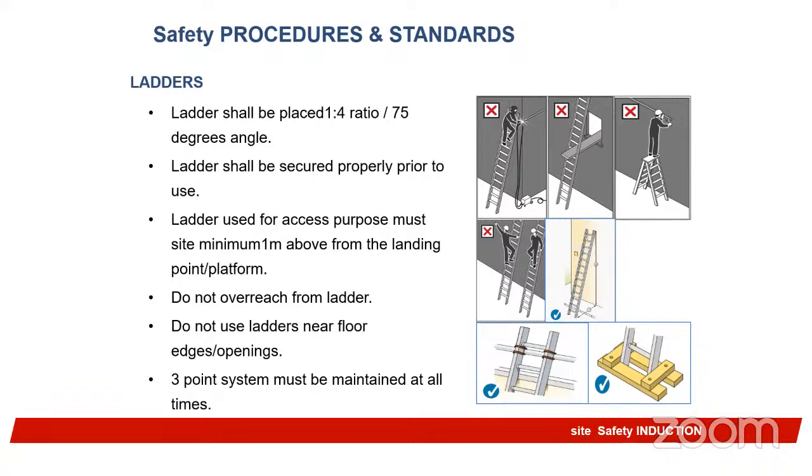You should not overreach while using the ladder. Overreaching is not allowed while using the ladder. And even while using the scaffold, overreaching is not allowed. Generally, in work at height, you don't allow overreaching. Overreaching is working outside the framework of that particular ladder or scaffold or anything you are using for your work at height. Do not use a ladder near floor edges and openings. The ground that you're using your ladder on must be strong, must be solid.